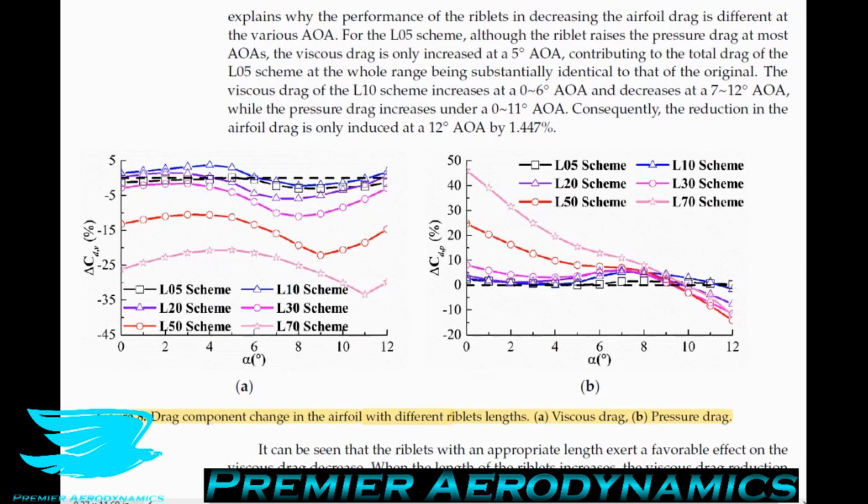They say the percentage of the pressure drag in the original drag is positively correlated with the angle of attack under the whole operating condition. So in other words, what they're saying is that for the pressure drag, the original drag of the baseline airfoil has a black mark here as 0, and everything else is correlated to that based on whether it increases or decreases it. And that's what we usually do. And the skin friction drag also has that same situation going on there.